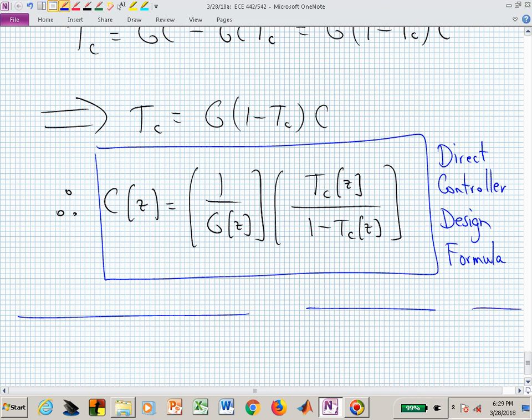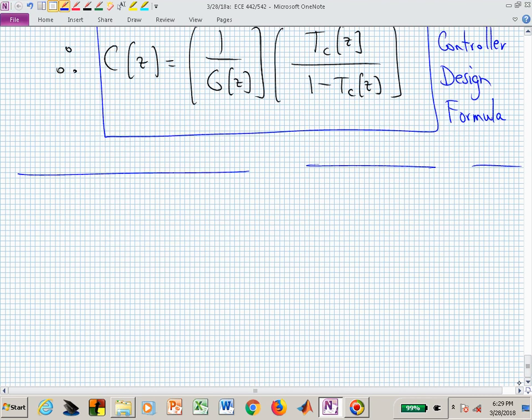We've talked about restriction 1. That forces the pole zero excess to be the same between our plant and our desired closed loop transfer function. We've talked about restriction 2 and restriction 3. Those are trying to make sure we don't cancel unstable zeros and unstable pole factors. Now we need to look at restriction 4.